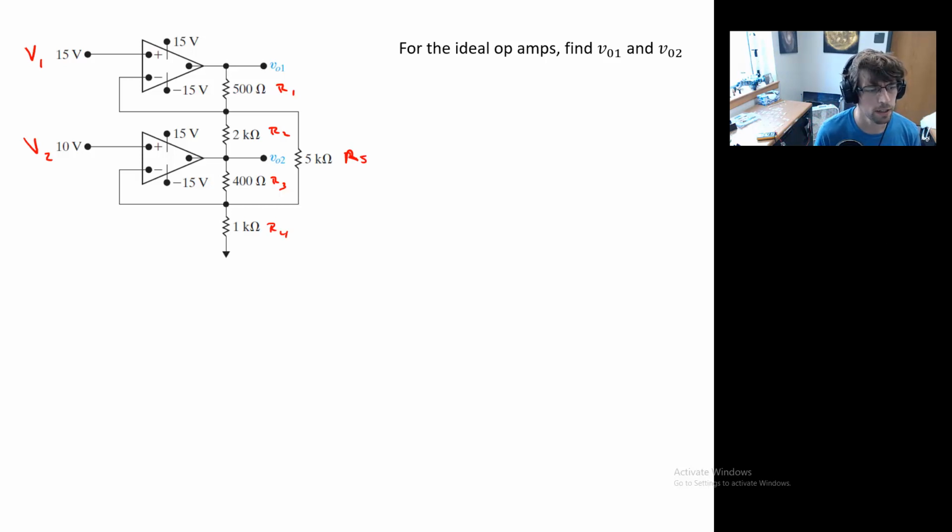So I have several junctions. I'll label them: I'm going to call this one node A, we'll have B here, call this one C, and this one D as in dog. And we have our golden rules. From the golden rules, we can immediately state that the potential at B is equal to, yeah, you got it, 15.